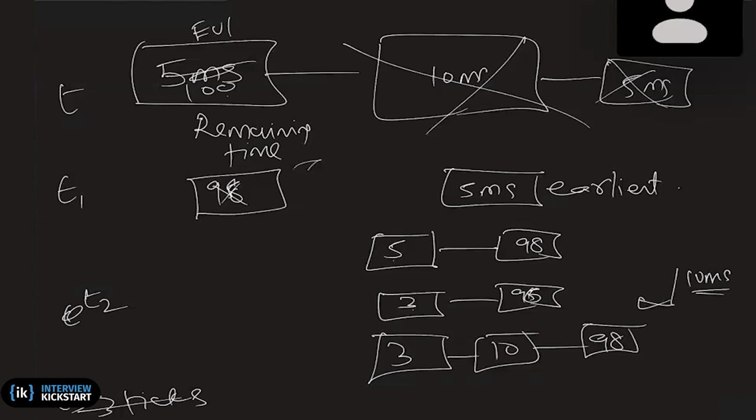Okay, a new timer value which is less than the current value is happening. Then the timer will be programmed for this, not this. You understand that there is one hardware timer. It is going to generate the ticks. The tick value will be reprogrammed from 100, or the remaining time of 98, to 5. The 98 will be turned off basically, because all you are interested in is the immediate event that will be expiring.